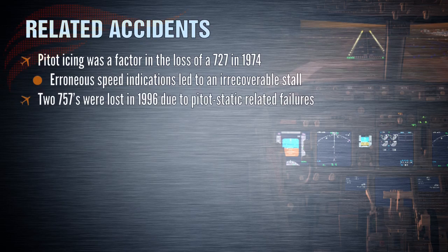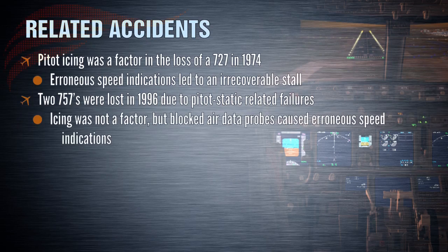2 757s were lost in 1996 following pitot-static-related failures. Icing was not a factor in either of these 2 accidents, but blocked air data probes caused erroneous indications and a subsequent loss of control.